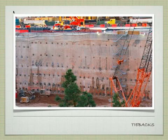So here's that giant excavation that I showed you several slides back. These are all those little tiebacks. They're going to vary at intervals. Notice they're a lot closer together at the bottom, a lot further apart at the top. The engineer specifies the placement of these. So you're going to engineer this foundation and this slurry wall. It's not just something that the contractor decides, oh, I'm going to put another one here. It's very specific about where those tiebacks go.